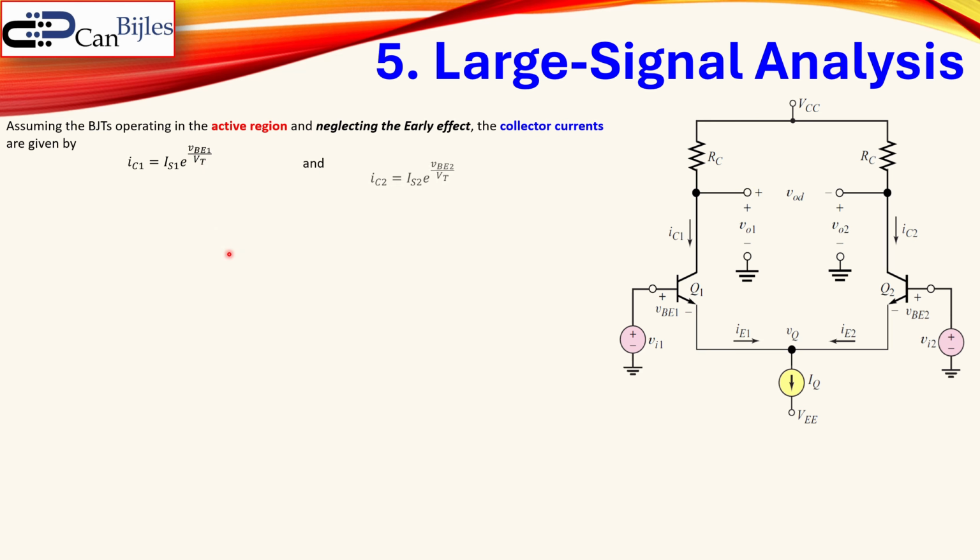Now similarly, we can do that for the IC2, which is the collector current of Q2. In a similar way, again, with VBE2. Now this is equation number 1, and we call also this equation number 2. Now for identical BJTs, so assuming both BJTs are identical, we know then that the IS1 and IS2 are identical because they are dependent on the parameters of our transistors. So we can assume that, and we can also call that IS, so no 1 or 2 anymore needed.